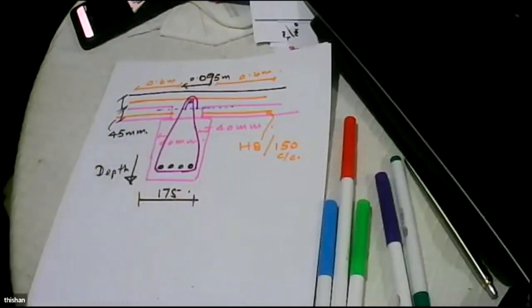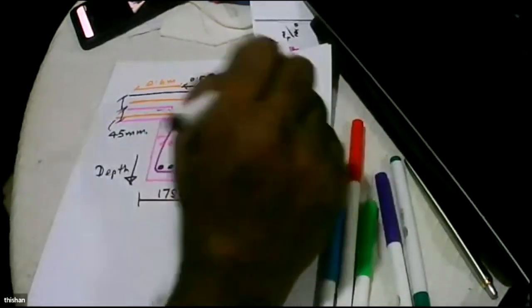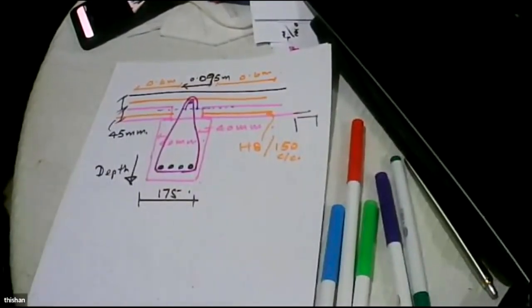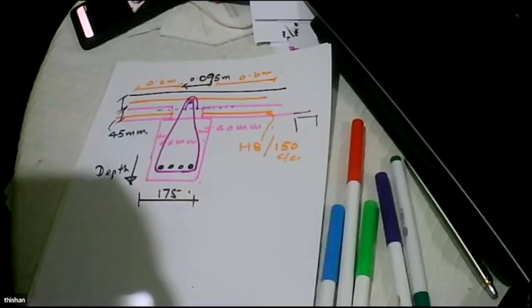And even for a 6 meter span, what becomes larger is the beam, but not the slab. The slab will remain the same 90 millimeter thickness and continuous over every 2 meters, where there will be either a wall or a slab. The other beauty is we can directly support this on a wall. So we can make it load bearing. Some of the walls can be made load bearing, and some of the slabs will be supported on the precast beams.